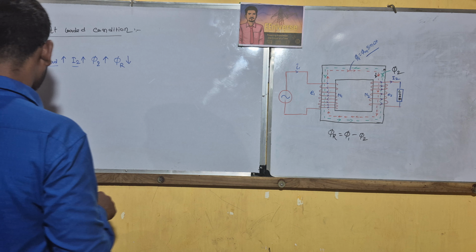And at loaded condition, I2 not equal to 0, I2 dash not equal to 0, and I1 equals Im plus I2 dash.